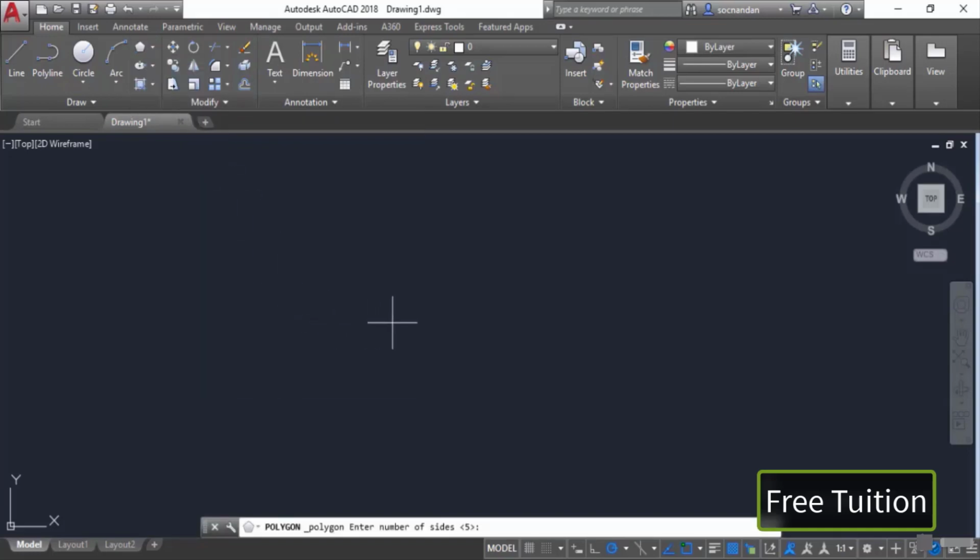Now after starting the polygon tool, you'll see on the command line we have an option which says we need to enter the number of sides. You can enter any value between 3 and 1024. So let's enter 5 and press enter. We are making a pentagon now, and you need to specify the center of the polygon. Click anywhere in the drawing area to specify the center, and now look at the command line.